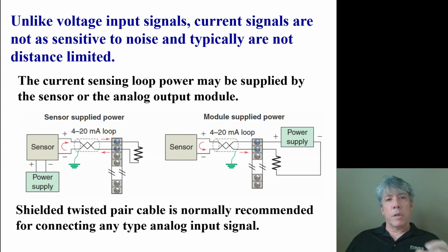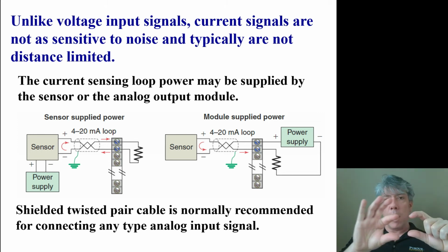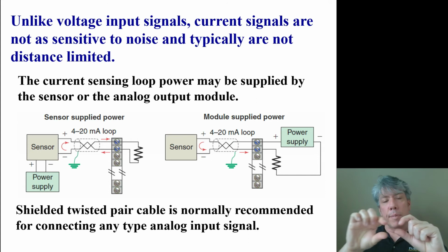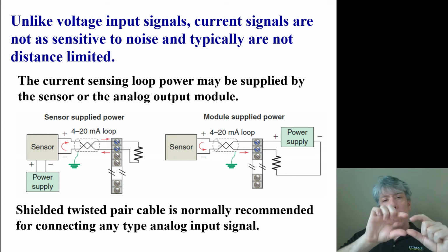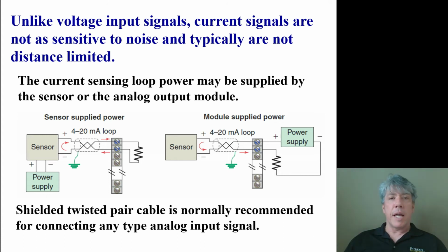Well, that's all well and good. The sensor may generate our voltage signal at the sensor, but if we connect copper wires to this, and those copper wires run for a long distance, those wires will have resistance in them. And if they have resistance, the voltage is going to drop as you go down the line. And so the measured voltage at the sensing end, where the PLC is, will be smaller than the voltage output from the sensor, and it'll look like the sensor is telling us a lower flow rate.